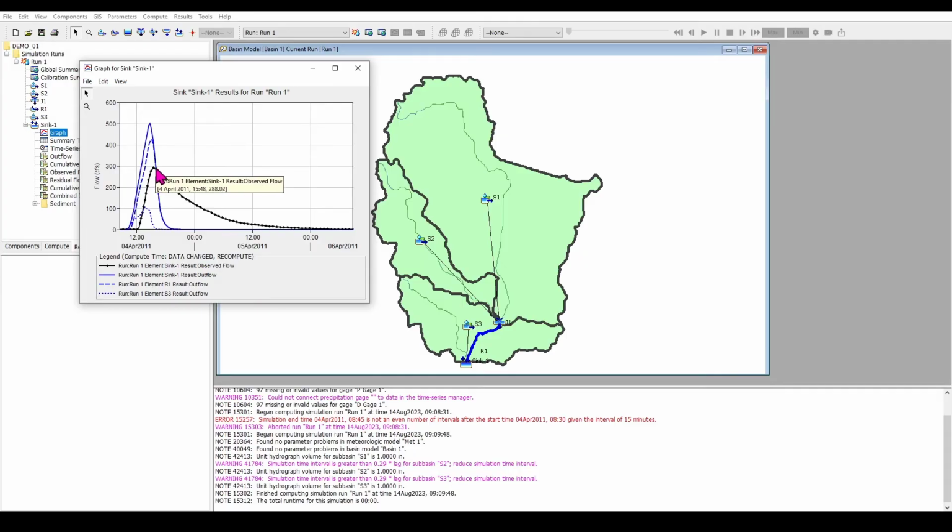This is telling you that you need to moderate the peak value of your simulation. And that's done using the methodologies that you have used for generating hydrograph. Remember the peaking factor? And I told you that the original number 484 is usually too high. So if you want to do manual calibration, you should go back and fix that.